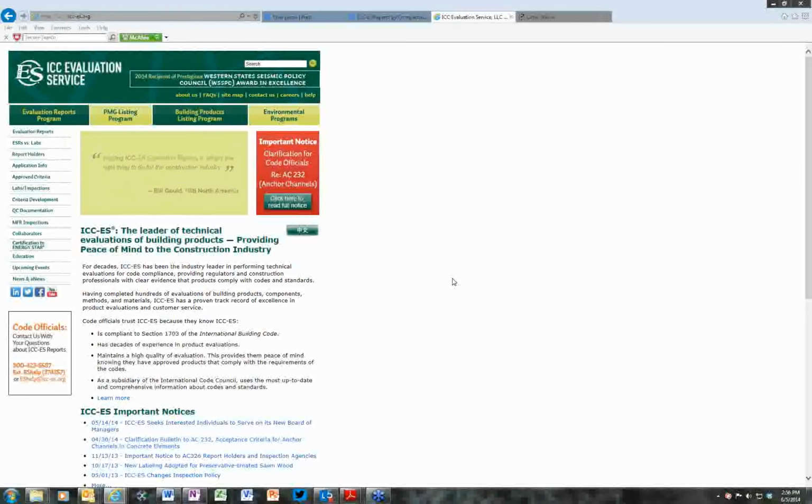Sure. Because the conditions for the use of the product in terms of its effect on other products is necessary, I think it's a good idea, for certain products, to have evaluation reports submitted as informational submittals, to have that information available so that everybody can see, oops, we need to have more screws in the gypsum sheathing, or we need to go to a thicker gauge on the steel studs.